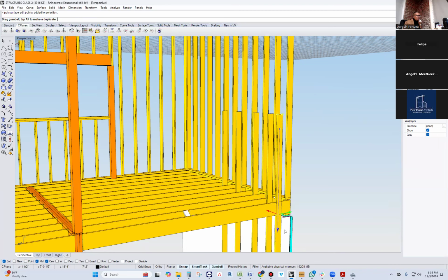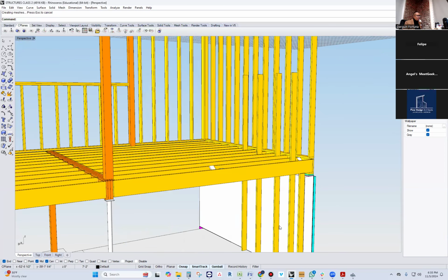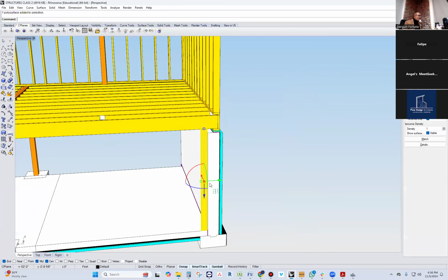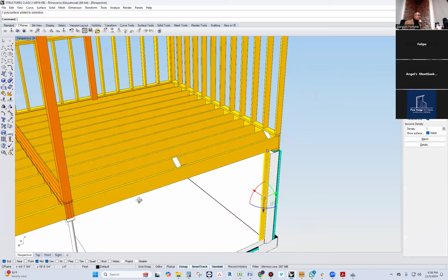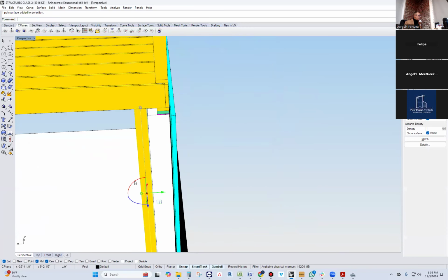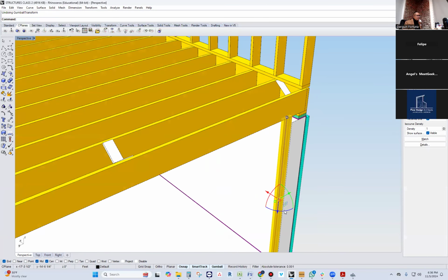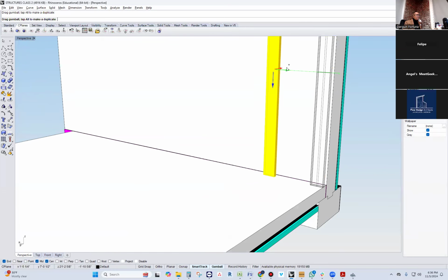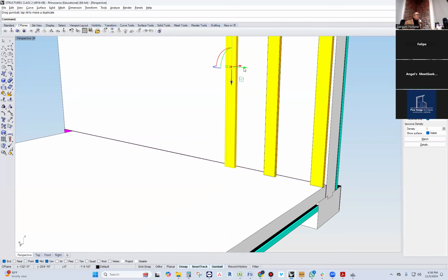You know what? I'm going to bring it all the way over here. And we're going to talk more about how we can frame those later. But you could use it on the flat when you don't want to lose a whole lot of square footage in your basement. You're like, oh my gosh, I don't want to lose a whole lot of square footage, it's very tight. So I'm going to do 90 degrees, like that, and I'm going to do it on the flat. And yeah, you can do that. You can literally put your members on the flat. That's what's called on the flat.